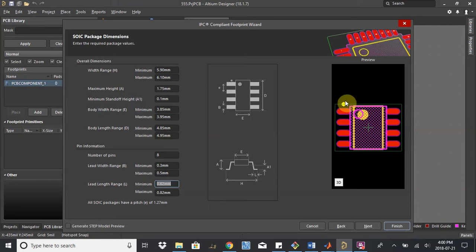You can notice this little dot here. All the lines in yellow indicate parts on the top overlay of the PCB. It's sometimes called the silkscreen. This layer is just to show reference designators like, oh, this is R56 or U13, and also any useful information you want to put, maybe your company's name or your name, or any notes or helpful guidelines you need to operate the PCB. This little dot will also show you pin 1 of the IC.